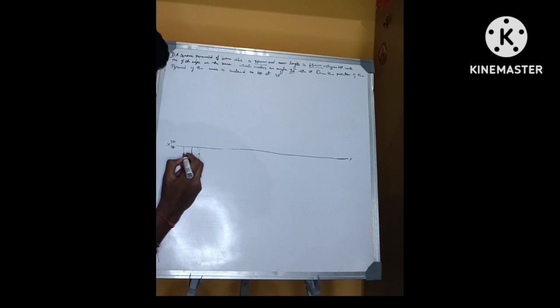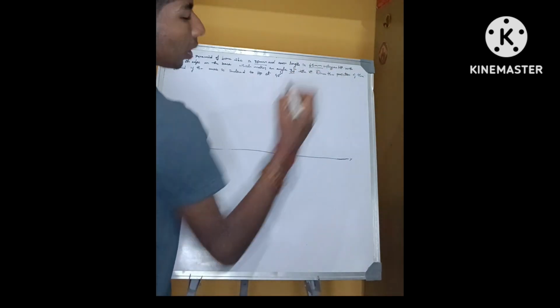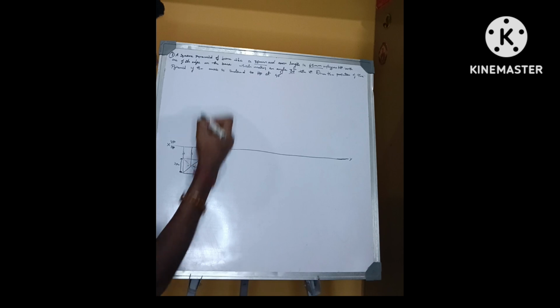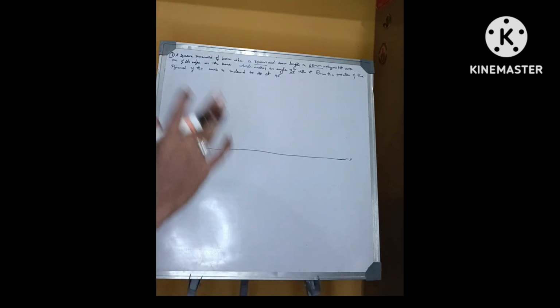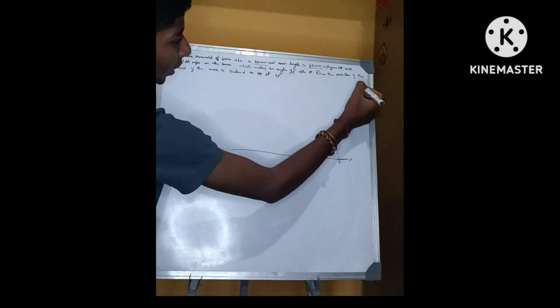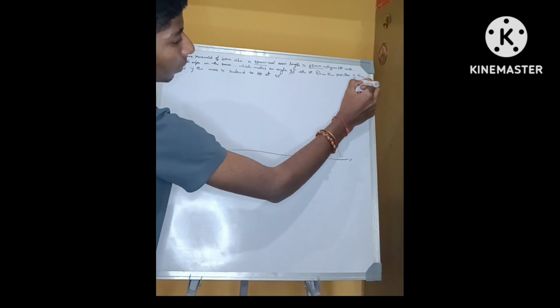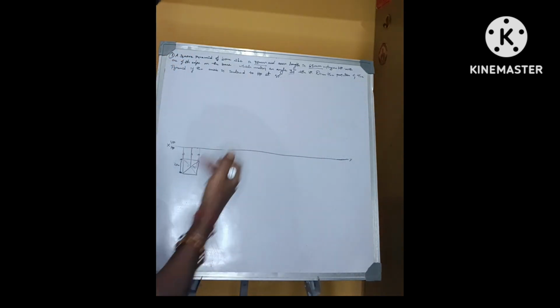Give the direction to the projection line. It is projecting upwards. Now you have to take the axis length as 65 mm. So from this point you have to take 65 mm length. Now make sure that the line is a chain line, which means it should be like this. Try to make sure of that.